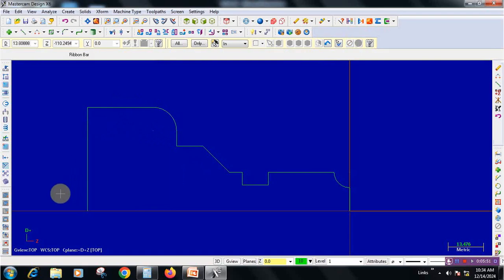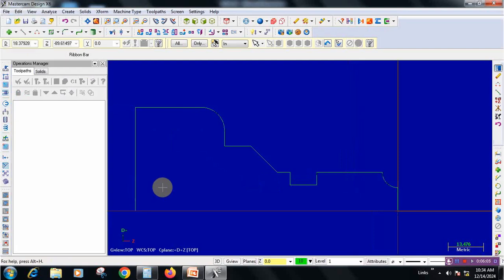Now we need to set the machine. So under which machine we are going to perform this operation. For that, select Alt plus O, just enter Alt plus O. We are getting Operation Manager window page. So here we are going to input all the informations like machine setup, parameters, toolpath, everything. So go to machine type, select a lathe operation, lathe default to be selected. We will get a machine group 1 and go to properties, say click on the properties.